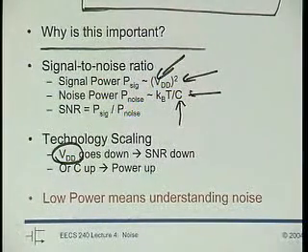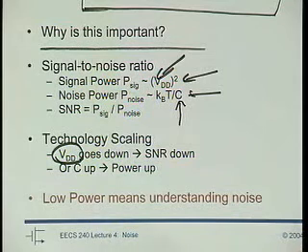Very big. Okay? But if we make C big, we're going to need a lot of GM to drive that C at a reasonable speed, and then the power goes up. Right? And so the question is, do these things just compensate? I mean, we have then also the more efficient short channel technology. Do these things compensate? Or net, is it a win? Net, is it a disadvantage or so?